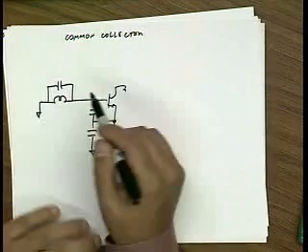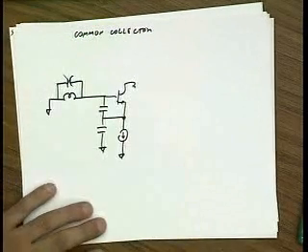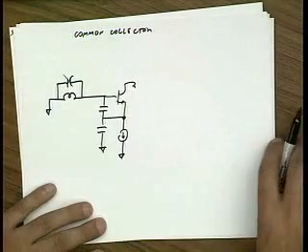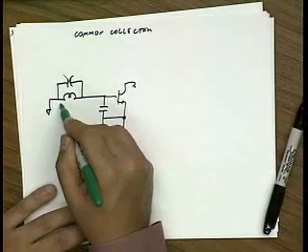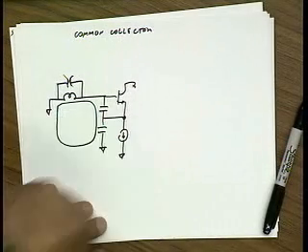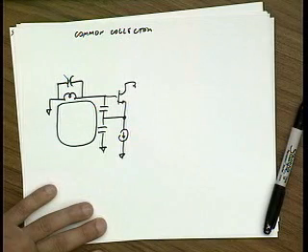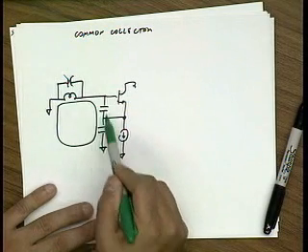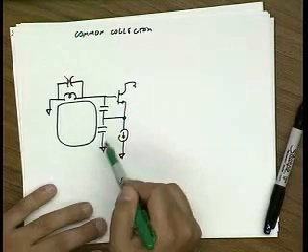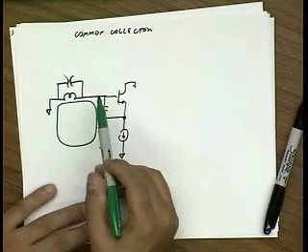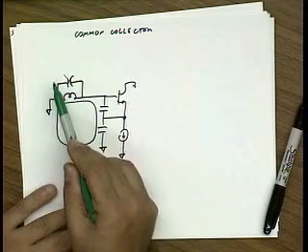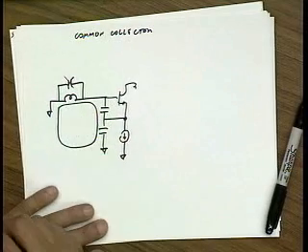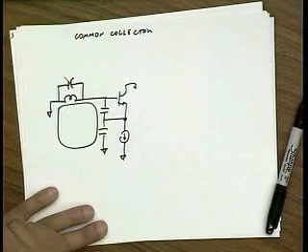If I get rid of this capacitor, the circuit still works because I can form a resonant tank like so. In fact, this capacitor can just be moved in parallel with these capacitors, and you can think of this as one net capacitor. So there's no need to put an explicit capacitor here. You can just make these capacitors bigger to make the total tank work.